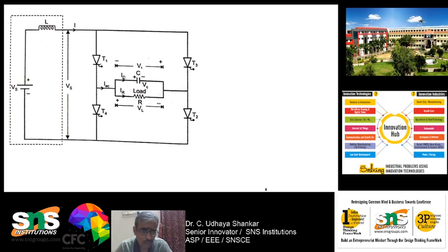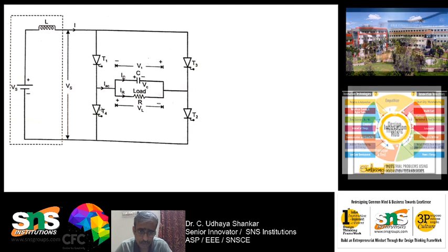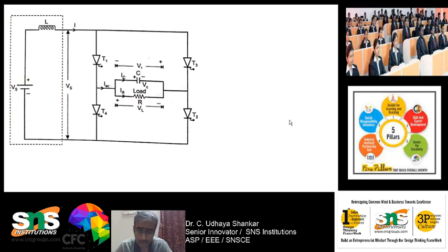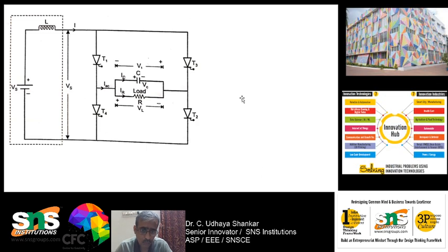So that's all for this capacitor commutated current source inverter, and you can just understand that when I switch on T1 and T2, I will be getting the positive current, whereas when I switch on T3 and T4, I will be getting the negative current. So I am getting an alternating output current, that is positive current as well as negative current, because of which the output current is AC, and similarly the output voltage also should be AC. So like this it goes on. Okay, so this is how it works.